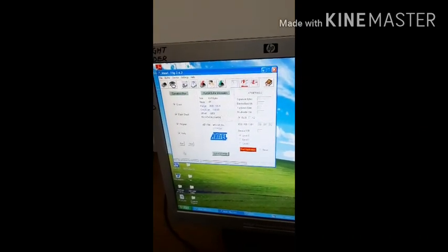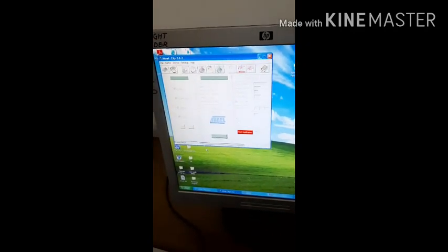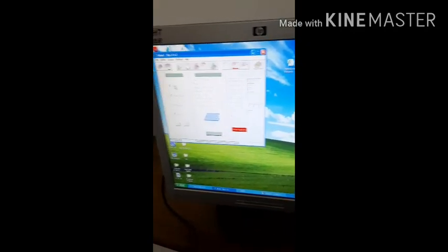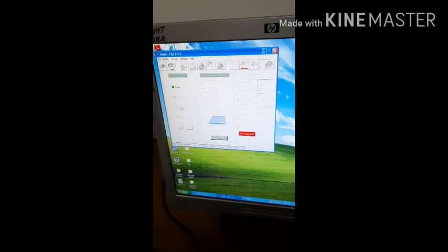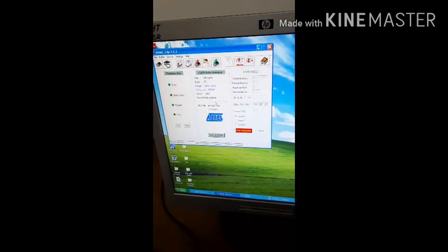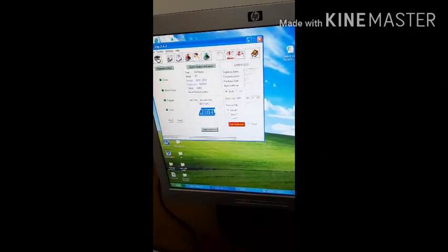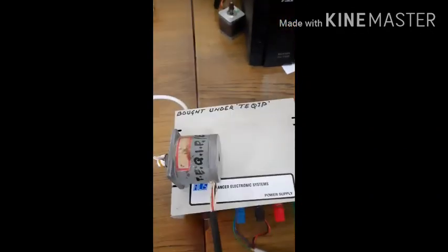So now once it is opened, as you know, I will have to run it. It will take a couple of seconds before it gets erased, then blank check is done, then the programming is done, then the verification is done. So now you can see here this program hex file anti-clock.hex is already loaded. Now if you look here, the motor does not rotate.